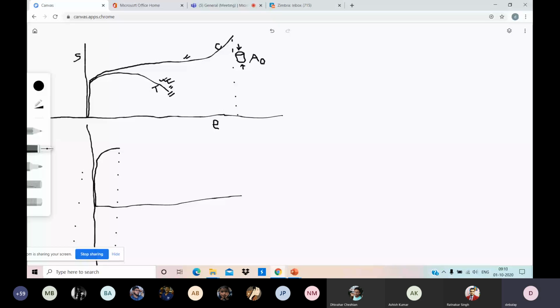So you have to explain what is happening in tension and what else is happening in compression. In tension, necking happens, right? Because of necking, why does your curve drop in tension?